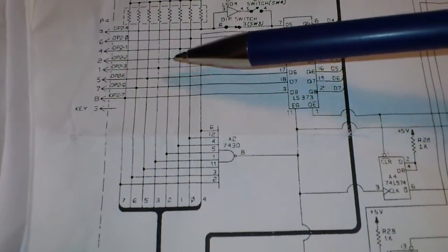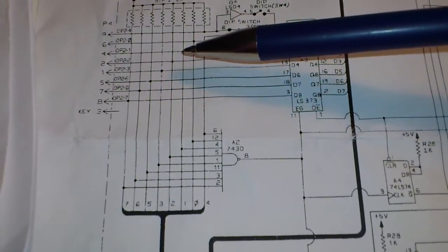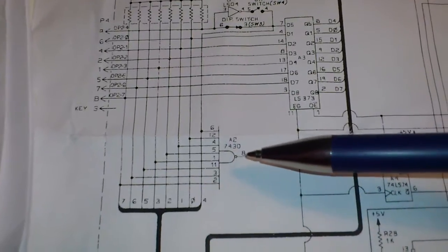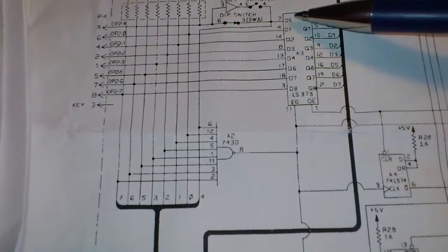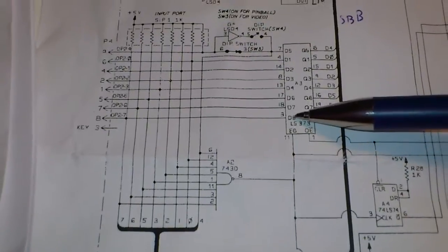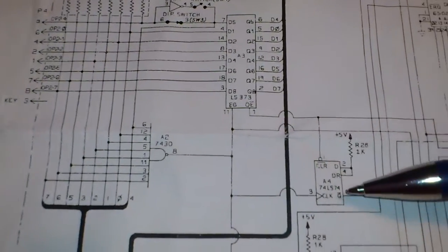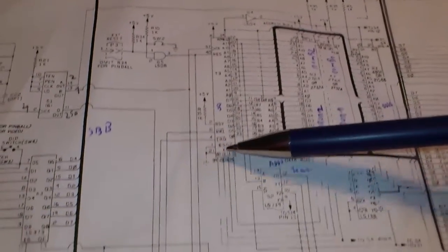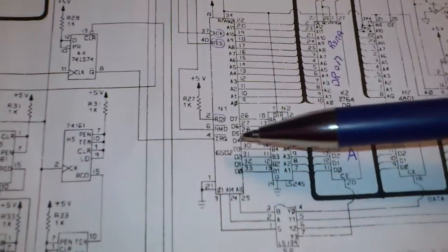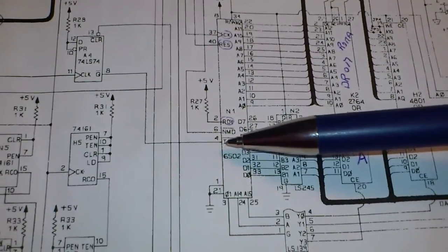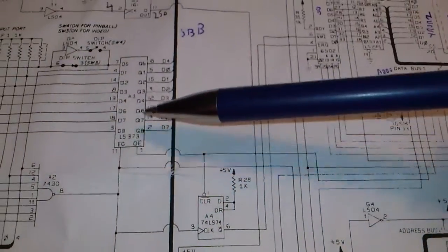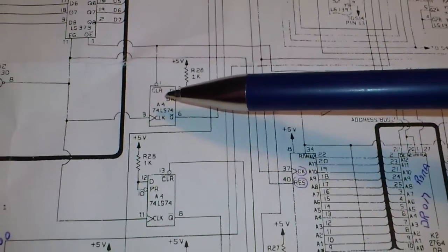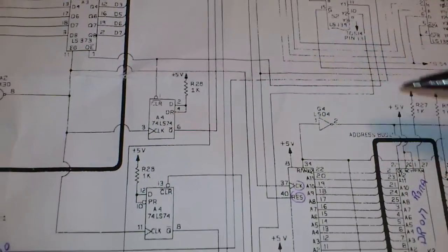If now one or several of those lines go to 0, which means there is a valid sound code on that bus, then a strobe is produced here. This strobe is latching the sound code into that latch here, and it also triggers an interrupt on both CPUs, on that line for the first CPU and on that line for the second CPU. The CPU then goes out and fetches the sound code from that register, and then it clears this D flip-flop, which releases the interrupt on those two CPUs.